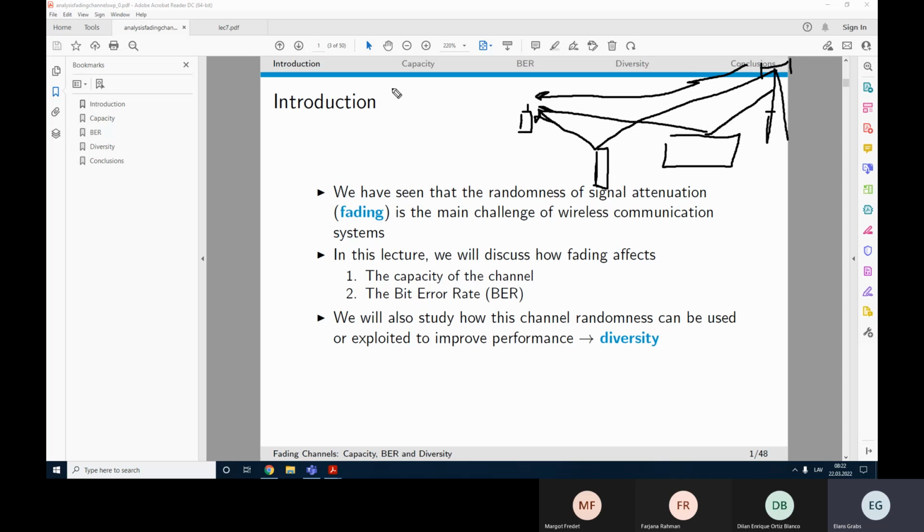And since we are using some specific carrier waves with specific frequency, called carrier frequency, reflected copies will always arrive a little bit later, and depending on the traveled distance, the phase shifts accordingly. We have this delta time caused by extra traveling time compared to the direct path, so we will have the signal arrive at different time moments.